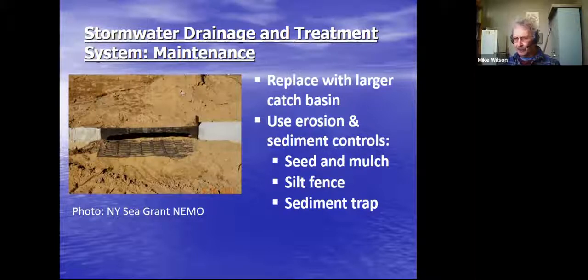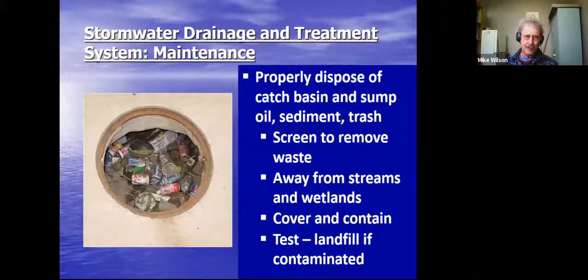You can seed and mulch or use a silt fence or a sediment trap. Anything to arrest and control that sediment from entering our catch basins. You want to properly dispose of this material. And if you suspect that it's contaminated, have it tested.